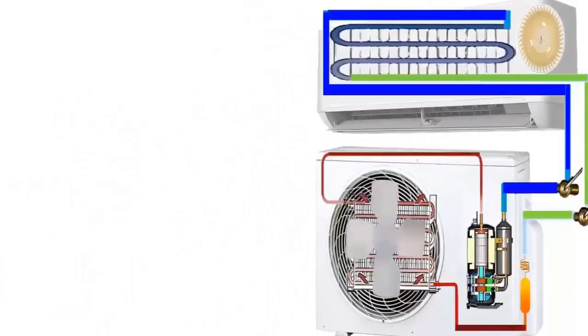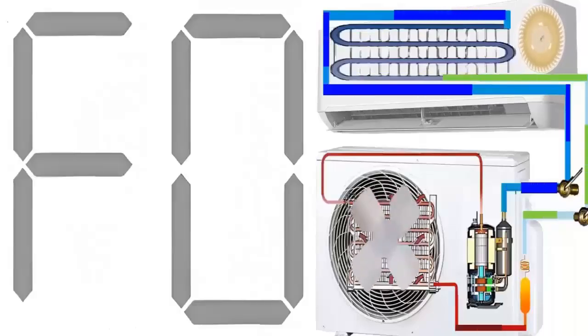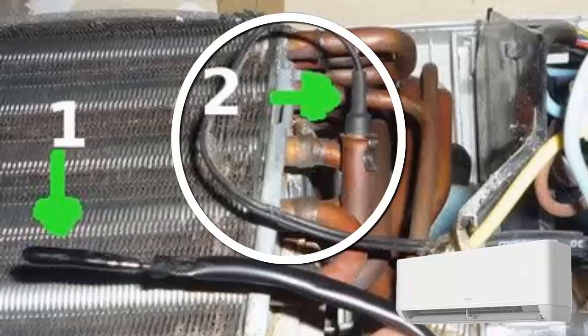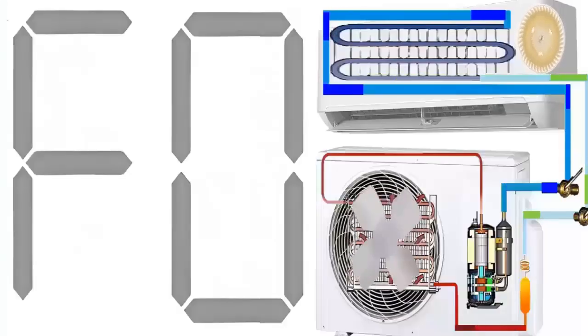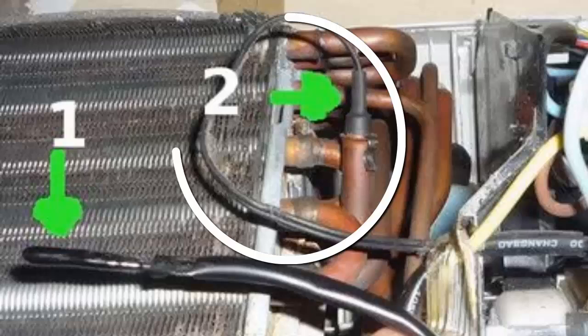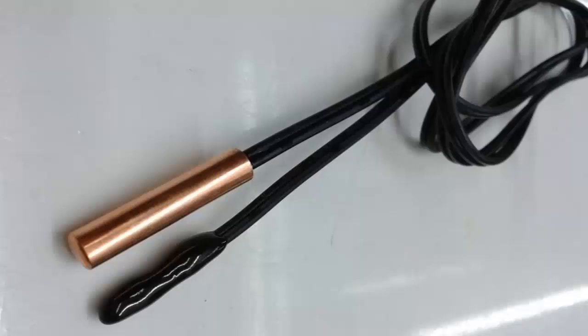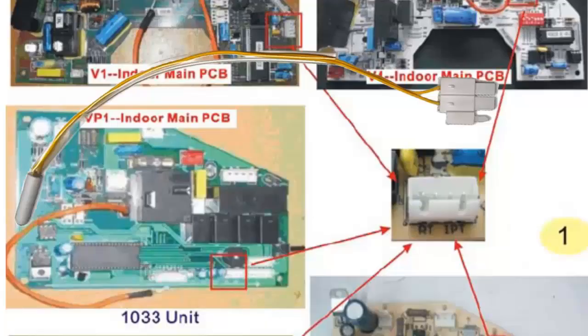4. To rule out a false alarm, focus your diagnosis on the evaporator coil temperature sensor, or evaporator sensor. 5. Check the correct position of the sensor and the condition of the cables that go from the electronic board to the sensor. 6. If the error persists, turn off the unit, disconnect the sensor, clean the connections, and reconnect it. Then, check again if the error still appears.